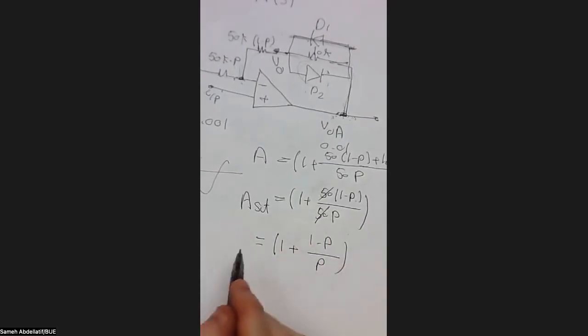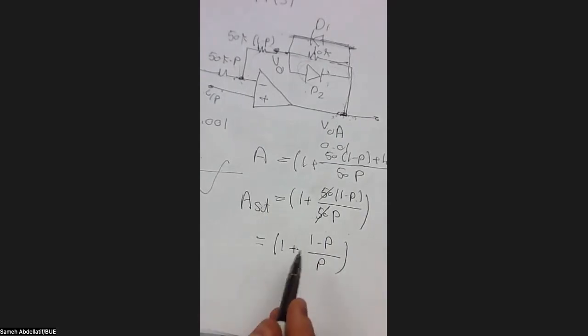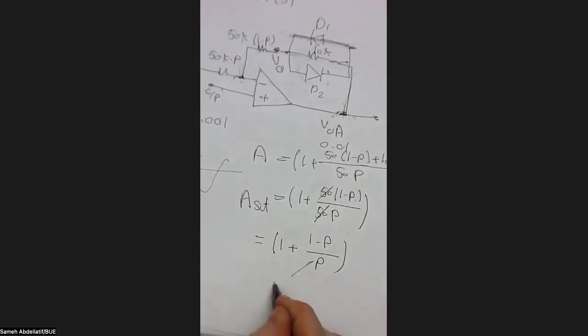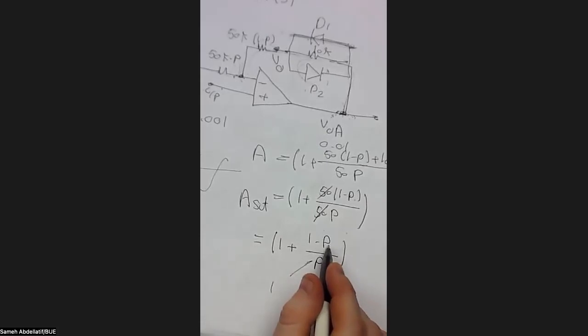So here, please return back to our previous recording regarding the control of the saturation gain. So typically you can manage whatever you want. Theoretically speaking, if you intend to make this saturation gain equal to 1, you can do it very easily by making B very, very high and 1 minus B very, very low, or simply by turning B to be 1. So 1 minus B equals 0, and then you will get typically a gain of 1.